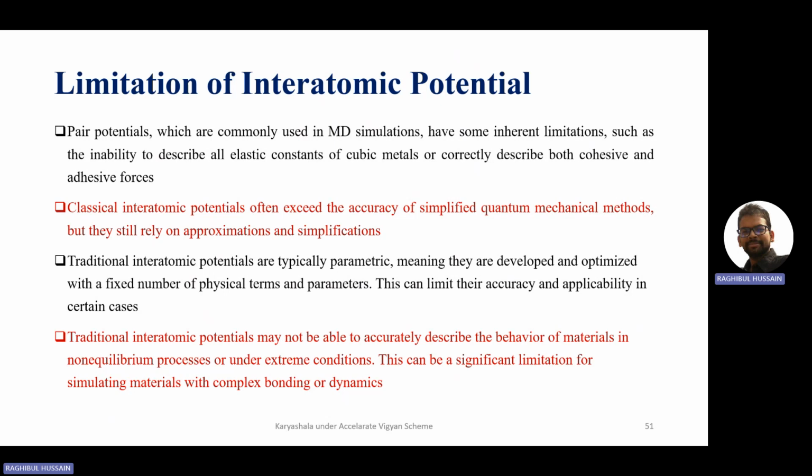Now, one of the practical challenges is simulating a cross-link structure. Whenever you have a very complicated cross-link structure, the cross-link joints, those connections, are not completely movable. So using the existing potentials or existing force field can give erroneous results.